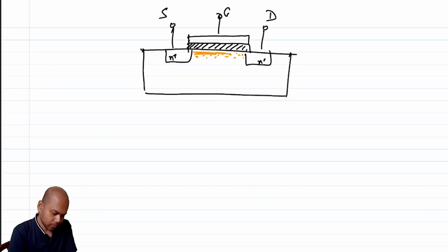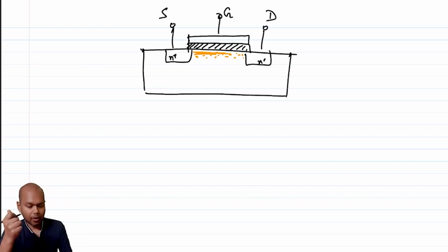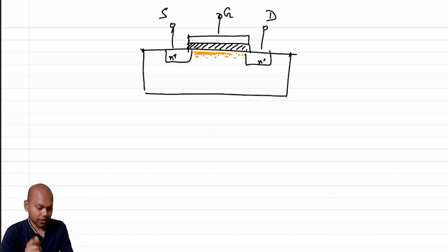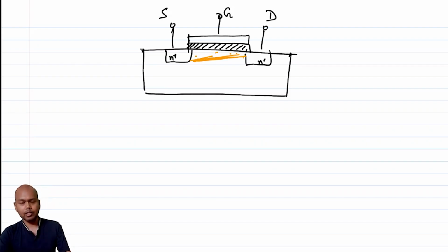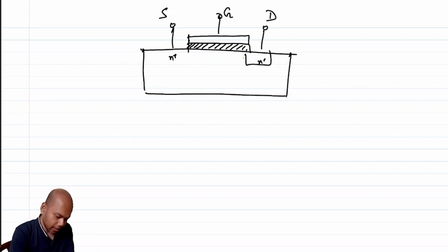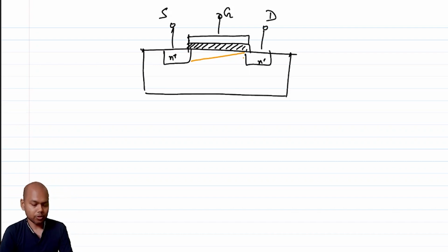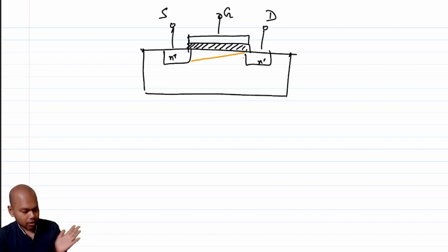And you have some gate voltage here, and then when you increase the drain voltage, the channel around the gate and the drain junction starts to get depleted, and you start to get a triangular formation, and at pinch off the channel totally vanishes at the drain side, right? Now think of it.